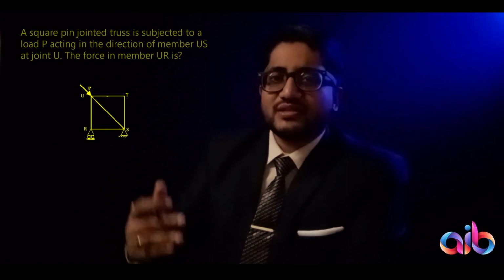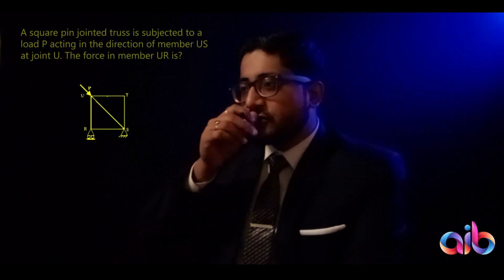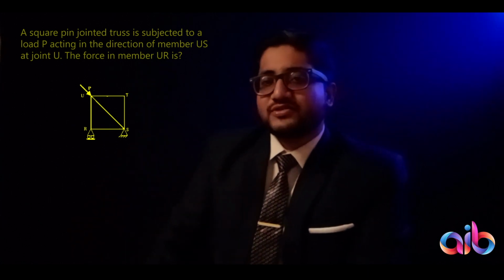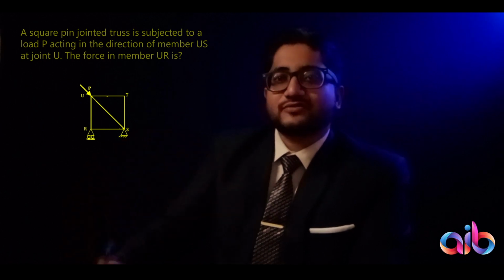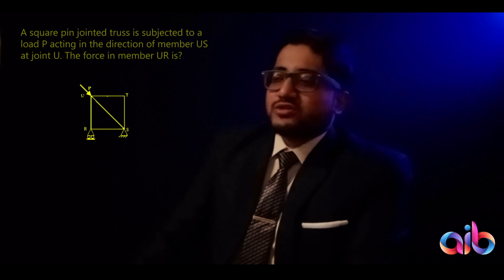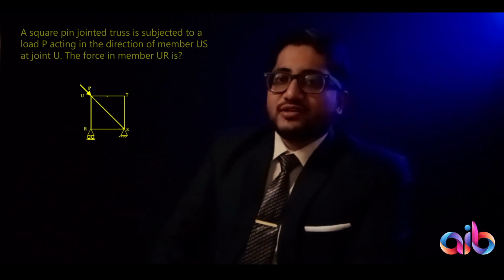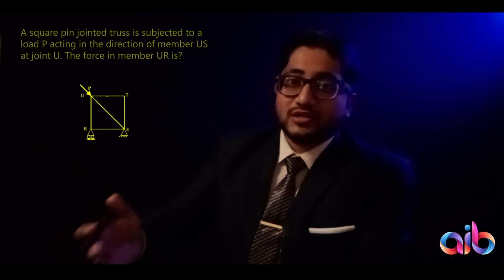You should be thorough with the concept of a zero force member and the two laws that guide how zero force members are identified, not calculated, because the entire law for identification of the zero force member is based on the presumption that you don't have to calculate. You just look at it and you know it's a zero force member. So this, as we can see, is straight away a zero force member. The countering force would be straight away collinear with the angle of the force acting on this truss. And the third one need not be at 90 degrees, it can be at any angle if you go through the law properly.